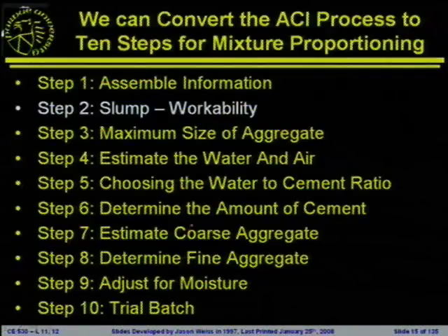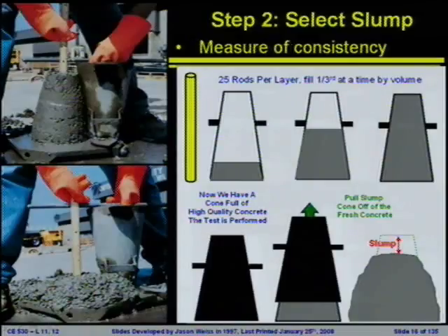Second step is to determine the workability. So we will use the very fine test of the slump test. If the slump test looks like a funnel that was sawed off and concrete was dumped into it, it was. This was used when the world's largest concrete canoes were being placed. In order to control consistency in the lightweight aggregate concretes that were being used in those destroyers that we were talking about earlier, they devised a test to say how consistent the mixture was. This is what they came up with. This test has been in existence ever since.